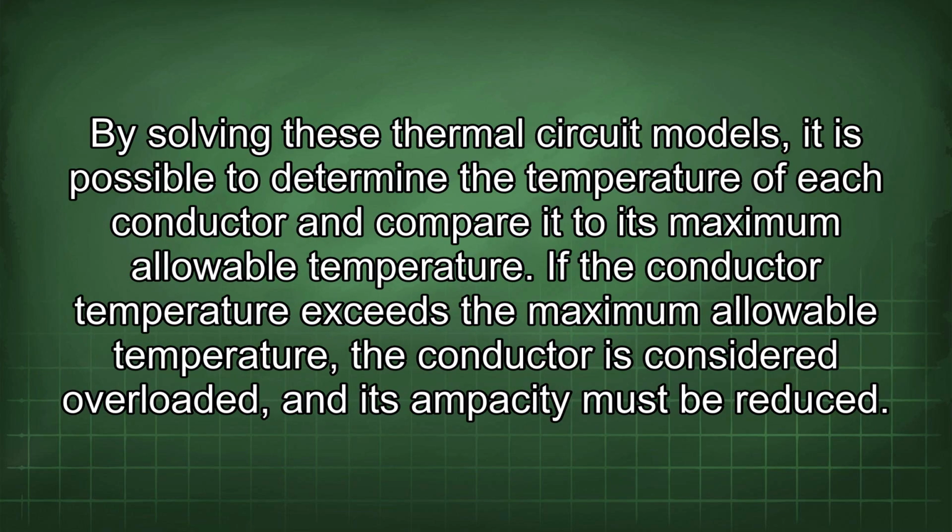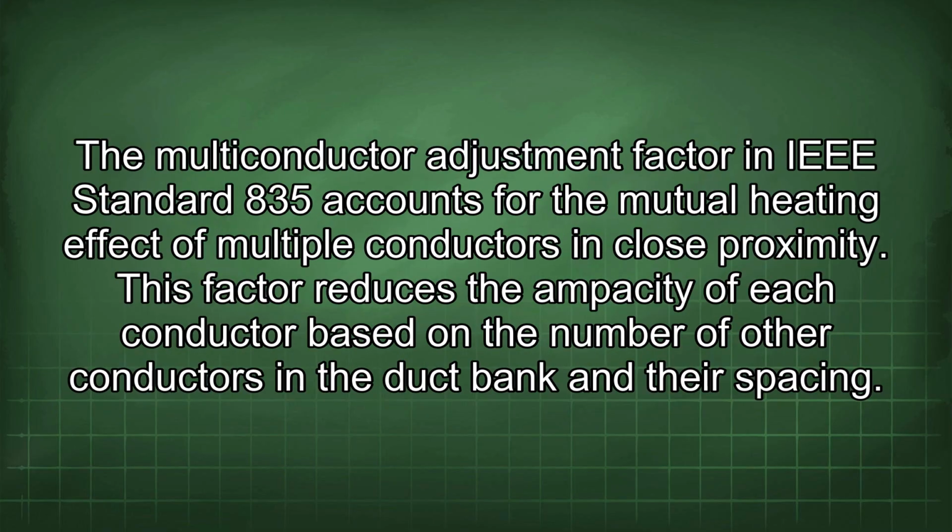By solving these thermal circuit models, it is possible to determine the temperature of each conductor and compare it to its maximum allowable temperature. If the conductor temperature exceeds the maximum allowable temperature, the conductor is considered overloaded, and its ampacity must be reduced. The multiconductor adjustment factor in IEEE Standard 835 accounts for the mutual heating effect of multiple conductors in close proximity.